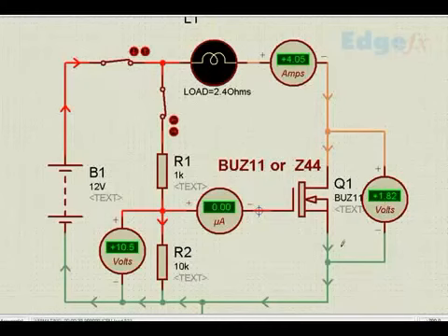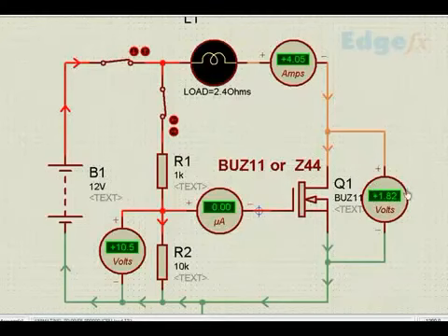So in certain places where we would like to protect, what we can do is take this voltage drop, and since we have discussed certain comparator arrangements, we can feed this to a comparator. Once a certain amount of current is exceeded, obviously this voltage will also exceed.